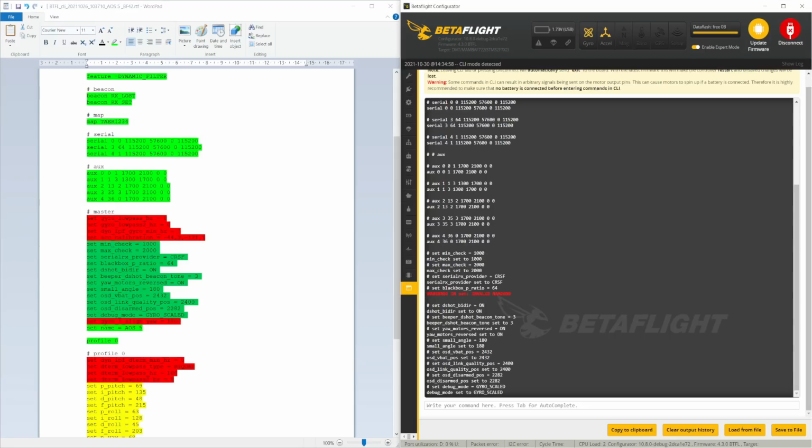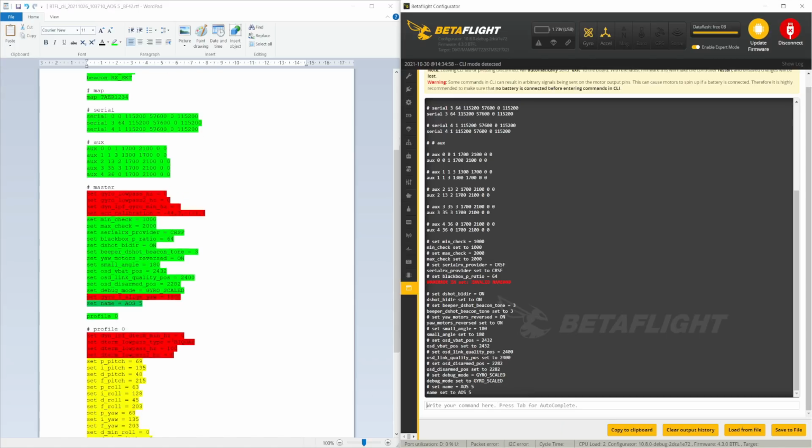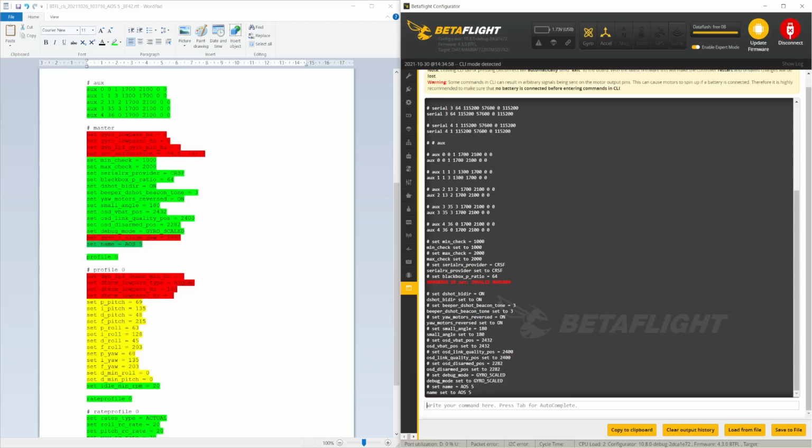Then we have another line with gyro in, so we're not going to paste that. But name is safe, so we're going to paste the name. Again, more dyne and now dterm lines, so we're not going to be pasting those in. Now, for the PID values, I think you probably can copy and paste those in if you're careful, but for this guide, we're going to be starting with default PIDs, and that's actually what I suggest you do as well.